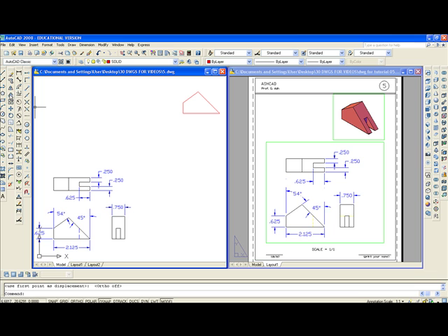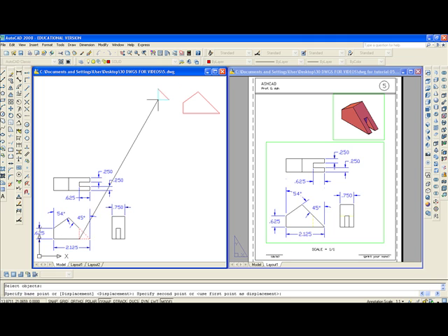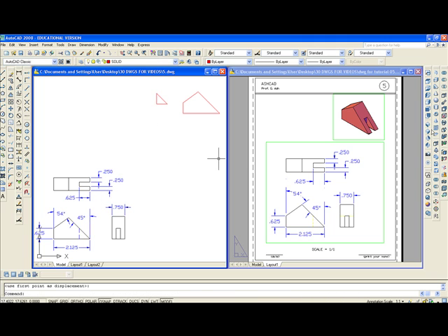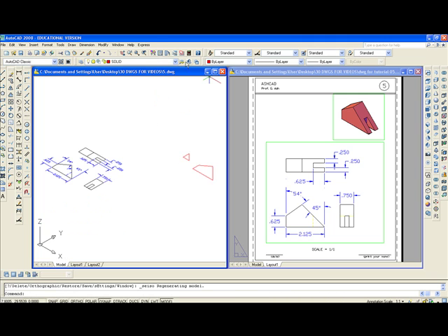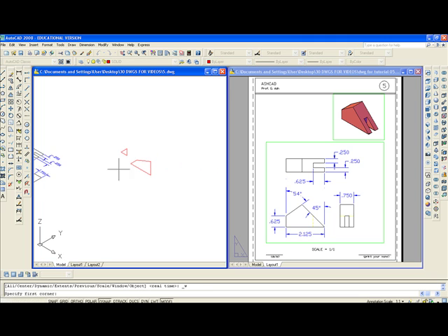You also want to trace over the little right triangle. So you take polygon, M, enter, L, enter, and move the right triangle up as well. And then move into southeast isometric, pan and zoom so as to enlarge the object.